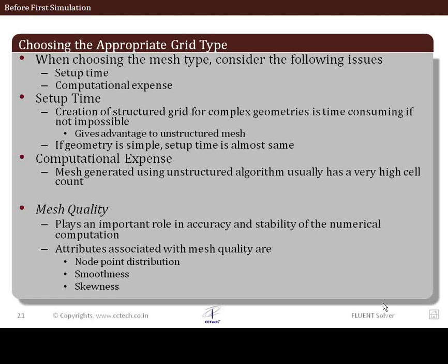For example, just to give you some numbers, if I have a mesh count of 1 million cells, then a 1 GB RAM cannot handle even a mesh for display purposes, leave aside solving the equations in the 1 million cells. So it's a very huge computational effort that we require. So we need to also handle these kind of questions before choosing what kind of mesh I should do the simulation on.